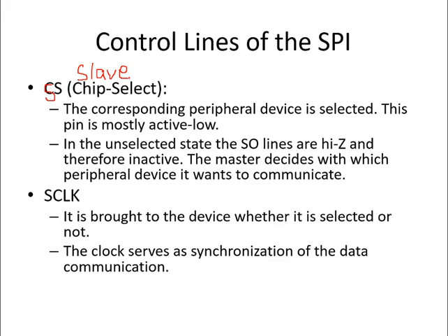The corresponding peripheral device is selected by this pin, which is mostly active low. In the unselected state, there is the SO, which means MISO. It is referred to as SO or MISO. MISO means master in, slave out signal.